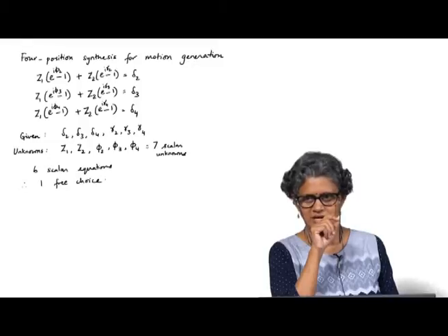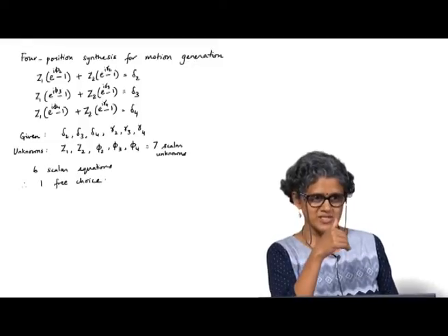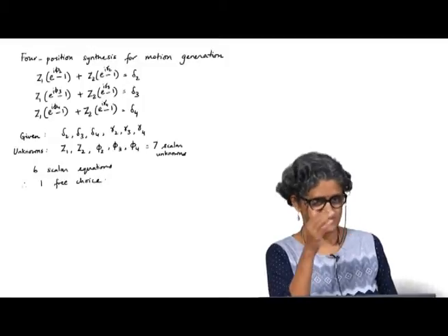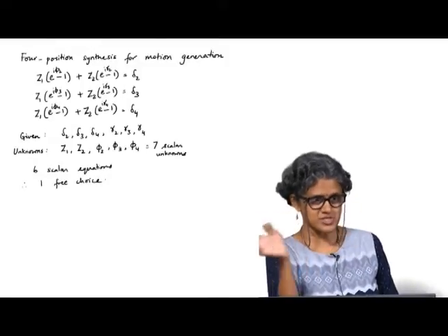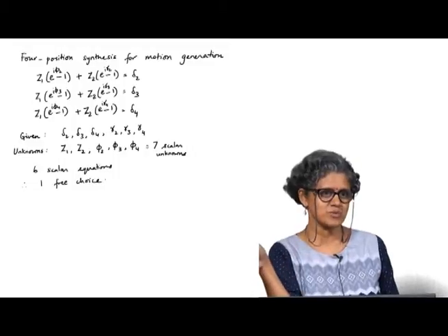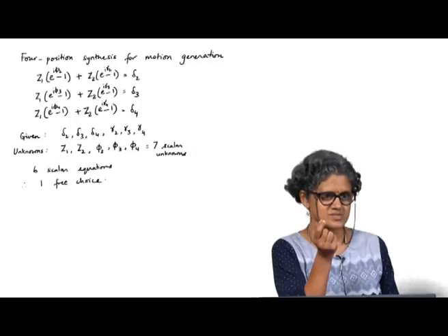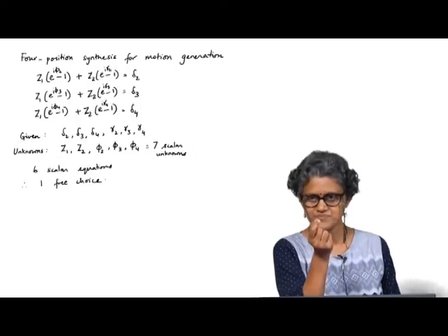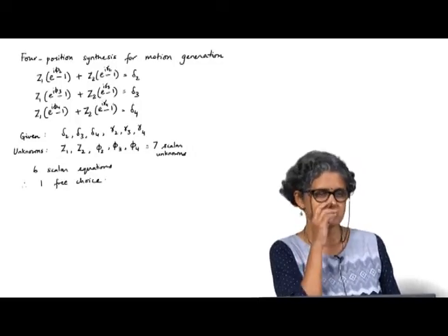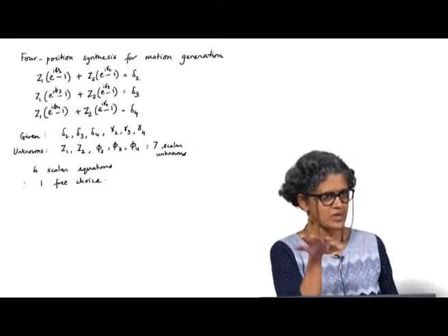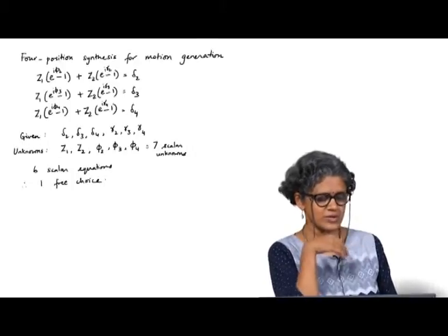So, if I choose that as a moving pivot, I can reduce the 4 position problem to a 3 position problem, because one point does not change between 2 positions. There are graphical methods for this, called point position reduction, but we did not go into that.